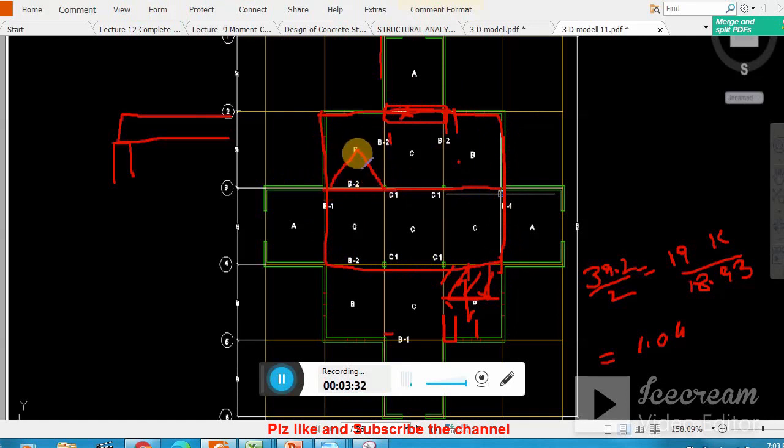As panel B and panel C are square panels, that's why I got this kind of graphical distribution, that is square. Okay, tributary area, and this is the triangle area load which is transferred to this beam, and this is the area which is transferred to this beam. This triangle will distribute load to this beam, and similarly this triangle will distribute to this wall, and this triangle will distribute load to this wall.